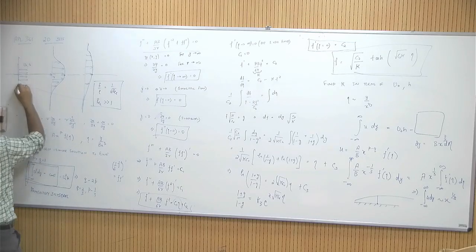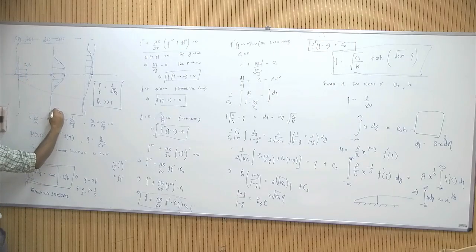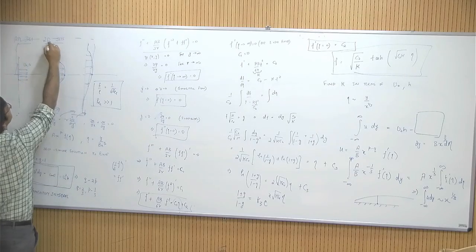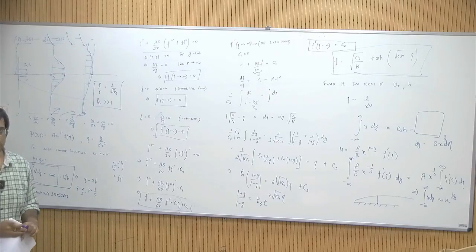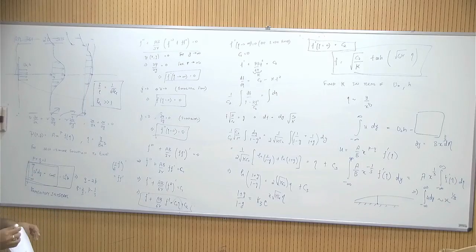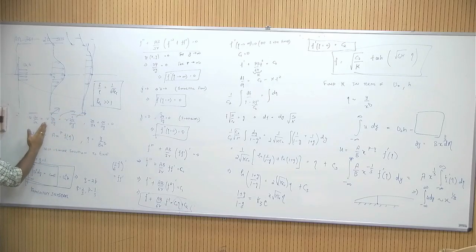Basically it is happening far away from the jet. What is happening is you have fluid that is coming in to the control volume. There is a mass flux from the side. That's why I was asking that the momentum integral, this entrainment flow will also have a contribution. No, because the thing is this is mass flux. In mass flux you have u dot n ds.